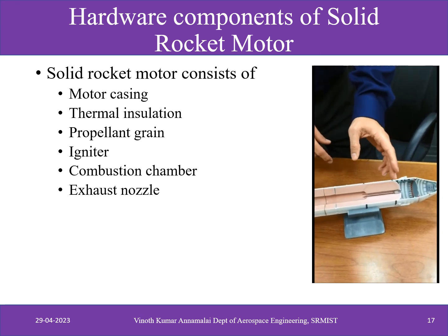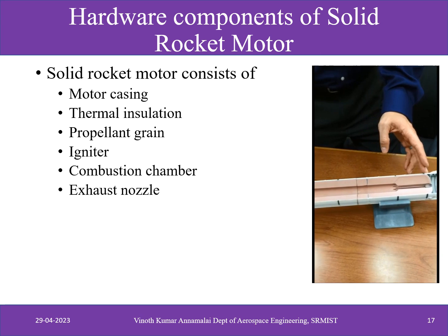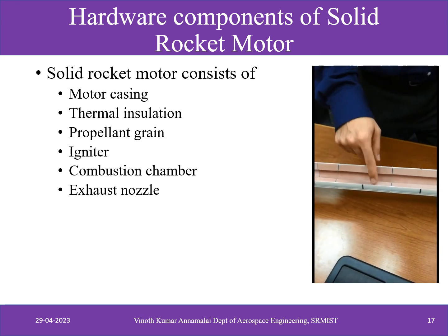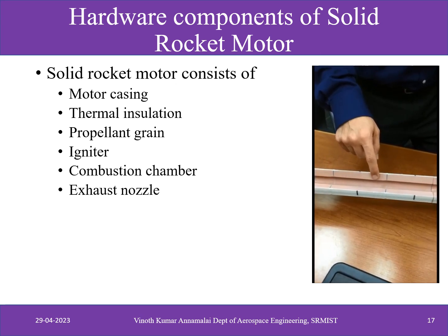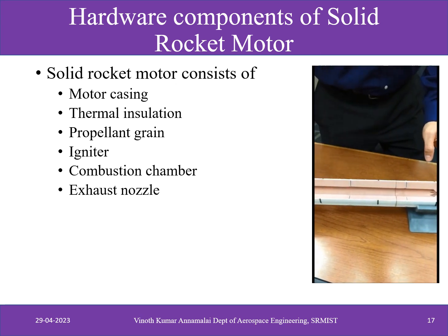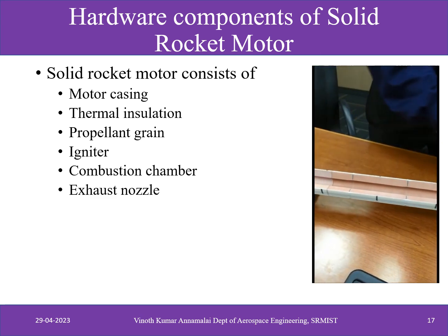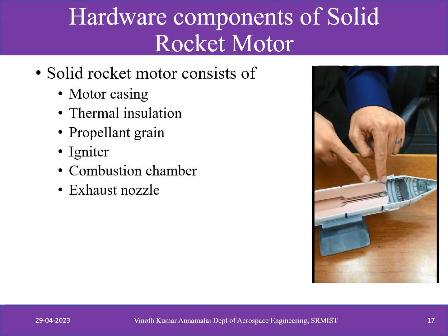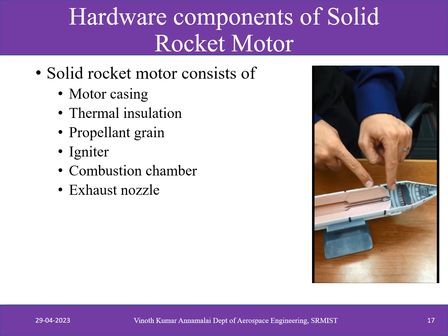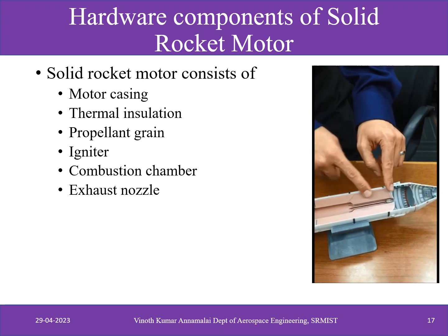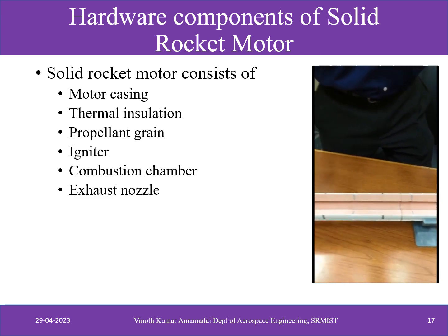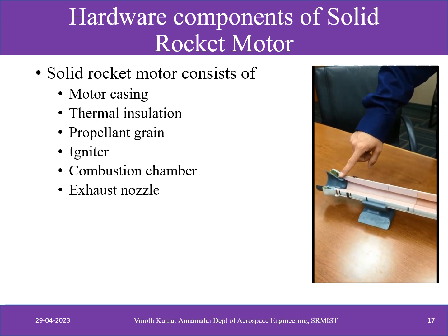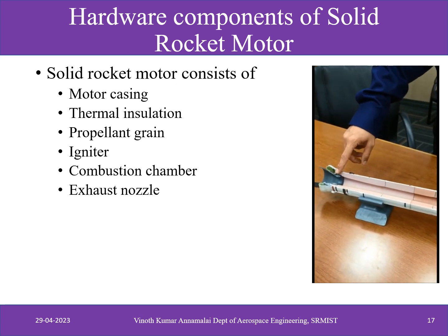Starting from here down, what we call these are 5 segments of the solid rocket motor. This is where you see the propellant is. So this is 12 feet in diameter, and most of it's propellant. You've got a bore or a hole going down the whole entire length of the motor. So right here by my finger up in the front end, though, you have what we call the igniter. It's like a small solid rocket motor itself that ignites and shoots a flame down the full length of this booster, or 150 feet of propellant, and it ignites all the surface of all the propellant at once, so that it all starts to burn together.